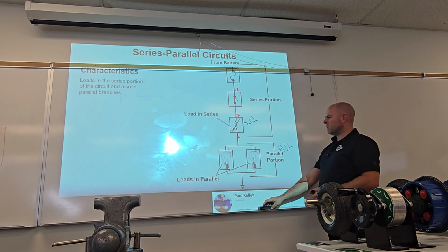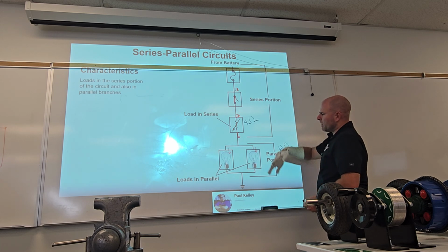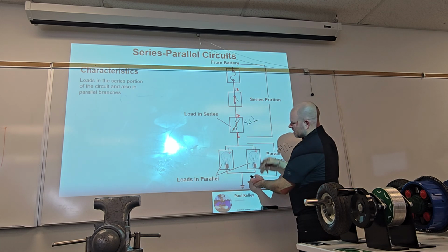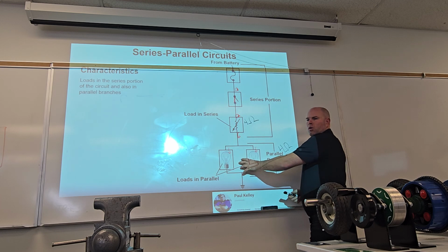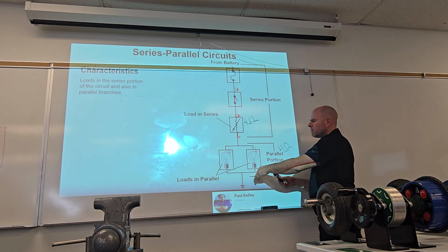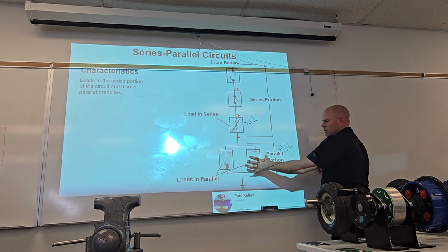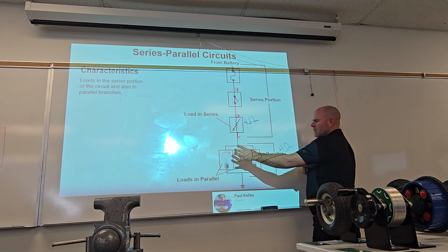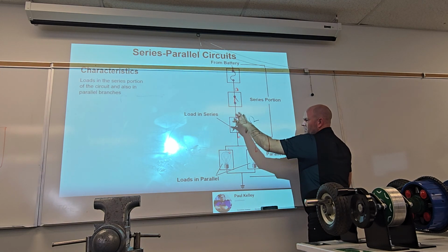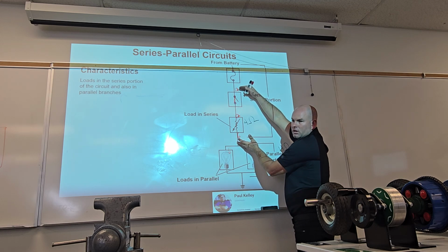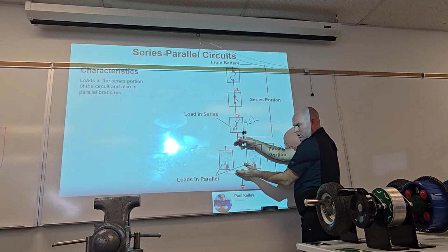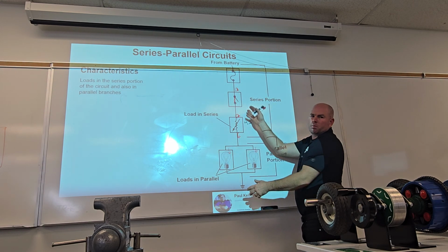So I want to simplify it, and I want to say, if you were to have both of these, that would mean actually these are more than 4 ohms. These might be like 6 ohms or something, but combined, the resistance becomes 4. So you could look at it like this, if this whole series part of the circuit is 4 ohms, and then the parallel part of the circuit is 4 ohms, they'll split at 50-50.